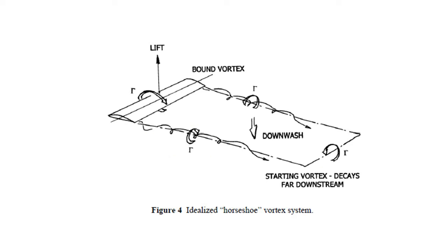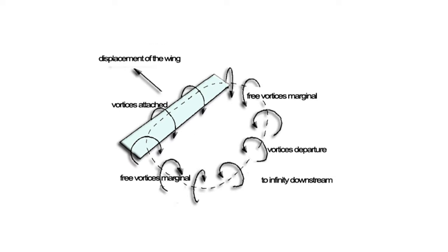It's also worth noting that there are more complete explanations here, which involve circulation in what's called vortex sheets extending from the trailing edge and running the entire span of the wing. But I really think that concepts like free and bound vortices and a few other concepts are out of the scope of a quick and digestible understanding like we're getting in this video. Wingtip vortices are really just the beginning of a whole vortex picture, because this is the first place that it really has a chance to occur.